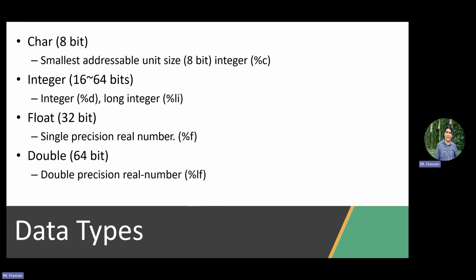What about embedded systems? Do you know what the width of your chip was in 241? 16 or 24, I don't think so. Okay, so what about Arduino? The smallest Arduino is 8 bits. It's an 8-bit machine. So what does it mean? We call this the machine width. It means that all the registers in this chip are 8 bits. Well, there are 16-bit Arduinos, there are 32-bit Arduinos. What about ESP32? 32 from the name, right? It's called ESP32 because it has 32-bit registers. What about our device, like the Nucleo board? It's a 64-bit ARM, which is a lot for an embedded system. It's one of the higher performance ones.